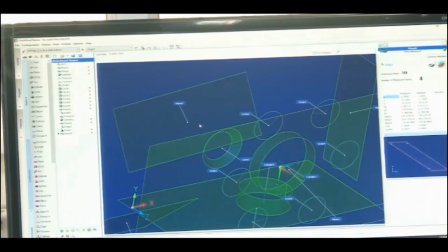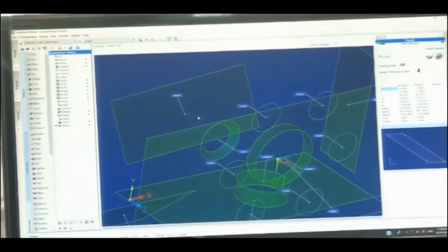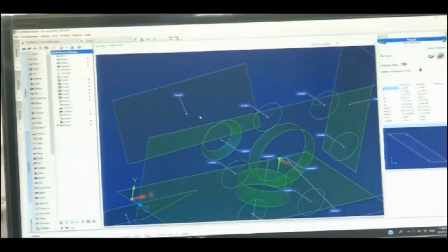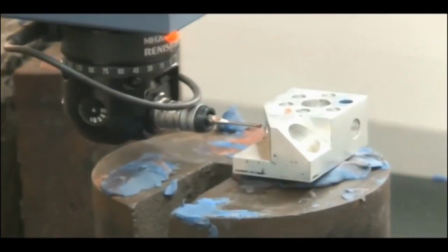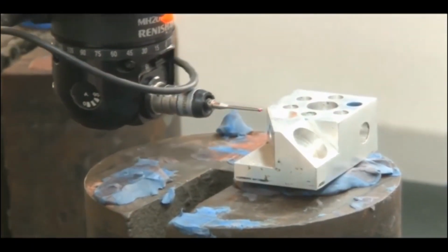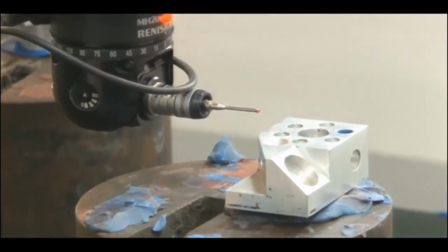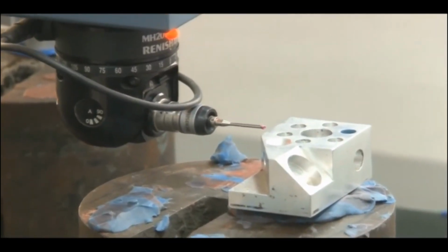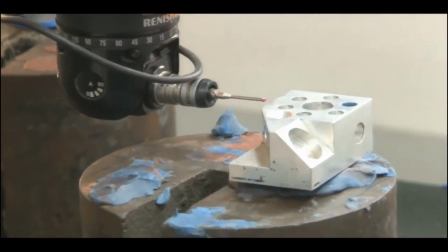we can measure all the parameters in different directions, in different features, of a structured form of the known parameters: cylinder, cone, all those things. Also free form can be measured. Okay. So, we can store the data files in IGS format. So, all these parameters can be exported, then we can save it to a file, all those things can happen.